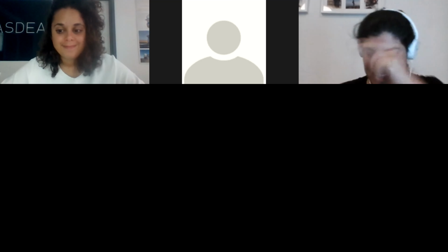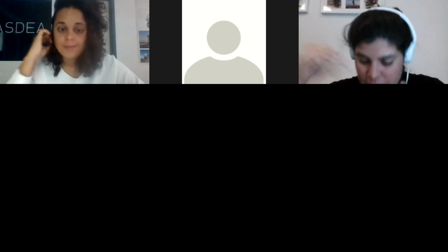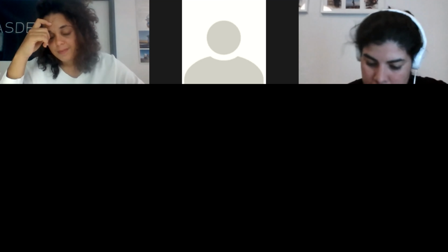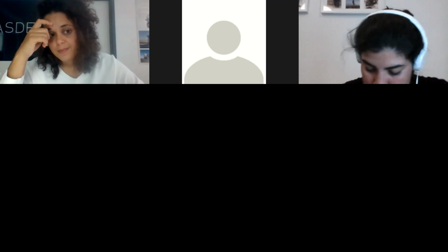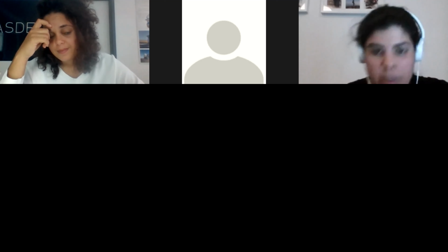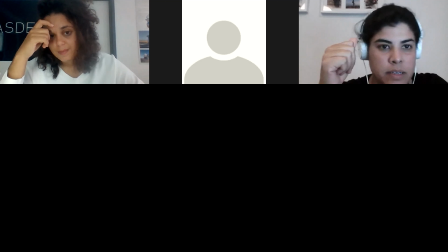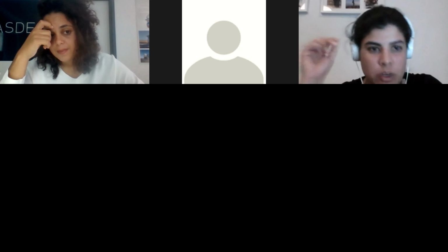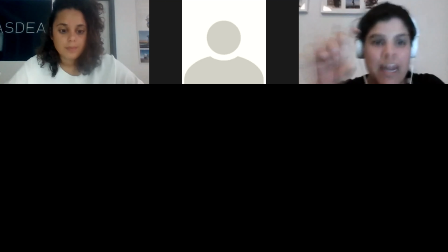Okay. I have three questions. The first one: when we speak about the lumped plasticity zero length, we said that we need always to define the hinge beam property and the hinge beam element. Yeah. And both apply to the node. No, to the column. Sorry, to the element, to this element.